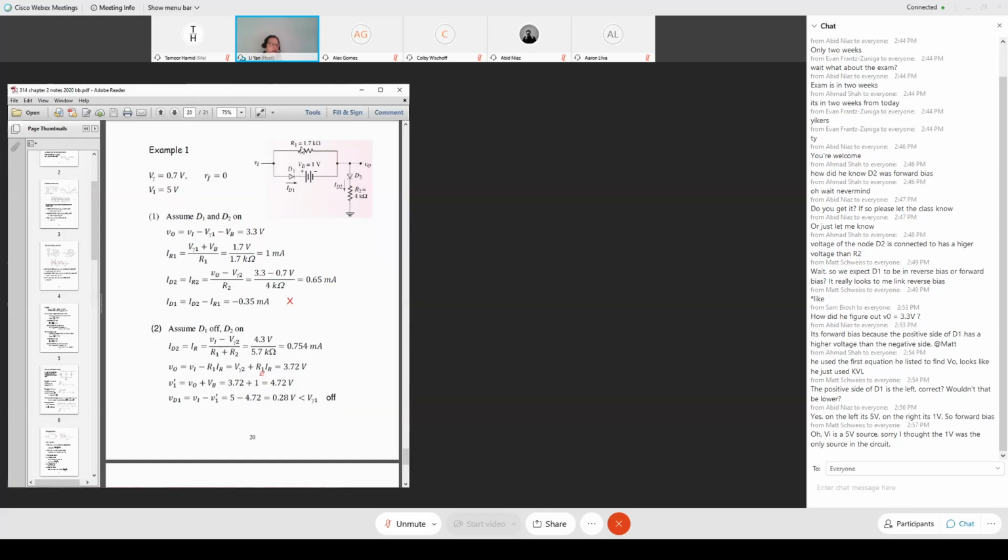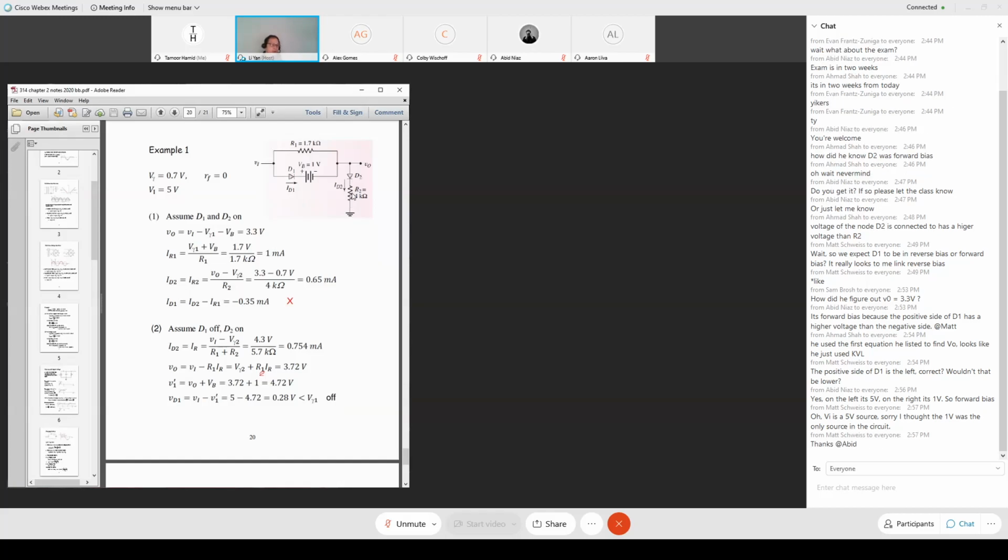Right? How do you calculate this current? I'm using Ohm's law. Ohm's law means I want to find out the voltage drop across the resistances R1 and R2, which I can find using the input voltage of 5 volts, VI. And if diode 2 is on, there's a finite voltage step down, V gamma 2 here. I use VI, subtract V gamma 2, and the remaining voltage is dropped across R1 and R2.